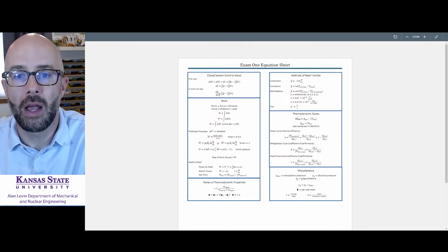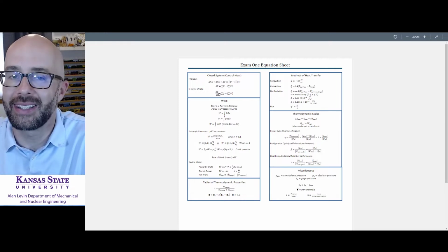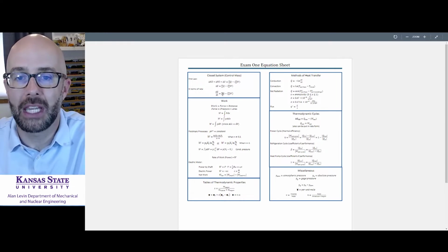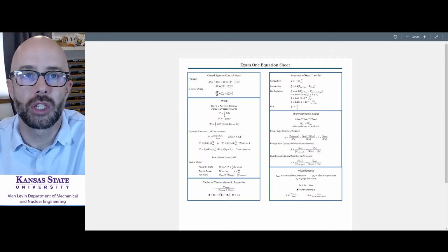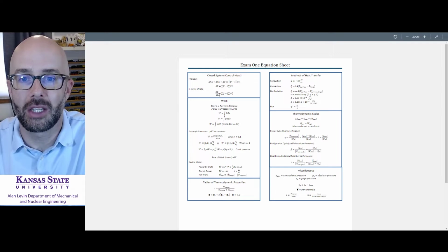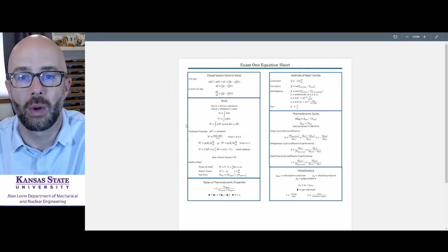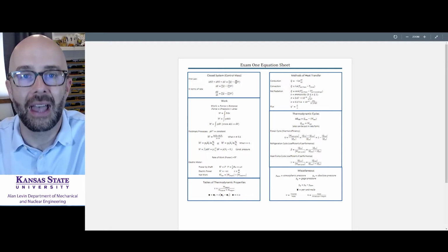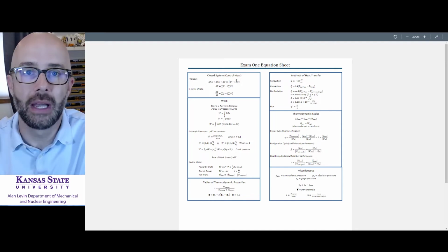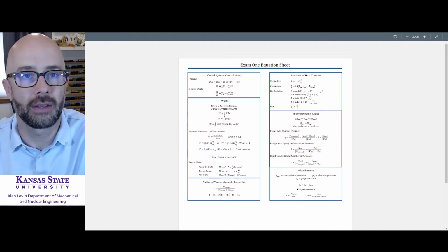In terms of rate now, we're going to say this is going to be the change in energy per time. And we've talked about what happens when this goes to 0. When it's steady state, the energy does not change with time. And we have the heat transfer rate. We have the rate of work, or the power that we're dealing with here. This is how we can work with a problem on rate terms. The key words you'll hear here is steady state. That means that this is going to go to 0 as you're trying to figure out what's going on. Now, note that every process has to satisfy the first law. It just has to. So note that you can do that for all the processes.